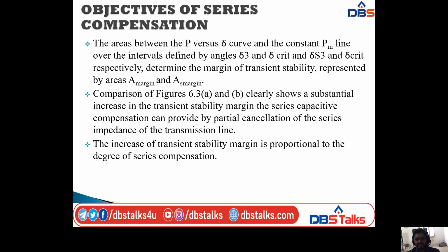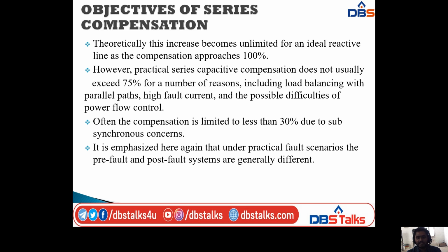The increase of transient stability margin is proportional to the degree of series compensation. Theoretically, this increase becomes unlimited for an ideal reactive line as the compensation approaches 100%.